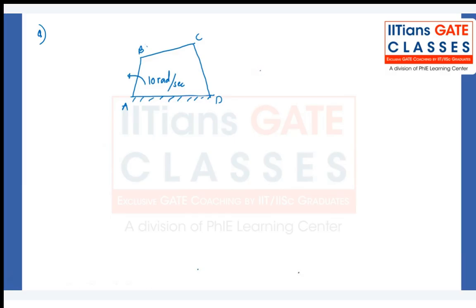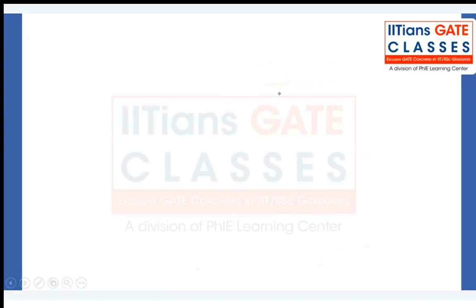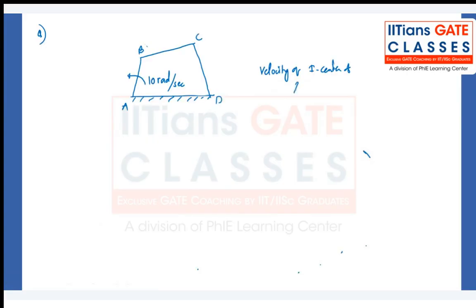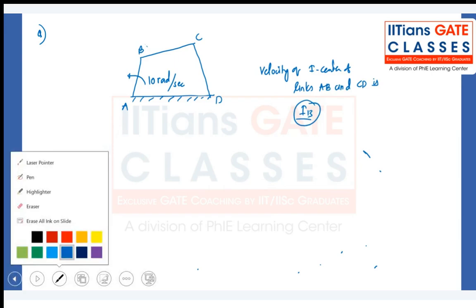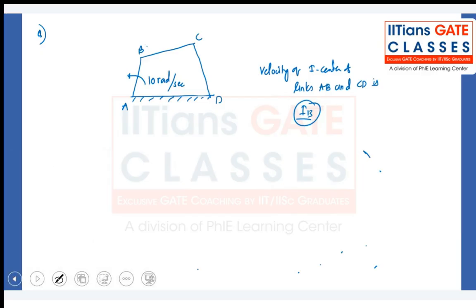I hope you are following. Velocity of the I center of links AB and CD. AB link is the first link and CD link is the third link. So I center 1, 3. They are talking about the I center 1, 3 velocity. So you know how to create the I center. The I center has to lie on this line, and similarly goes here.